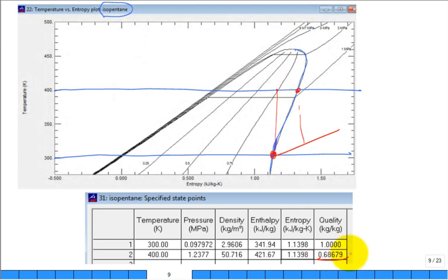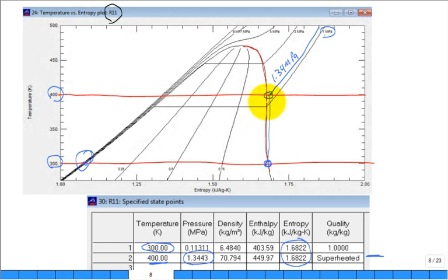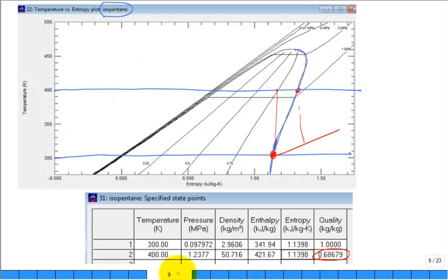The theory would say, oh, you could start expanding when all of it hasn't even boiled. That's probably not good, to start expanding at 70% quality. So it would be better to pick maybe a fluid that has a characteristic that is very steep in there. Well, I wish I had more time to explore these types of design considerations. Basically, you're mastering in this class the ability to make the calculations. Hopefully you think about the calculations and the implications.